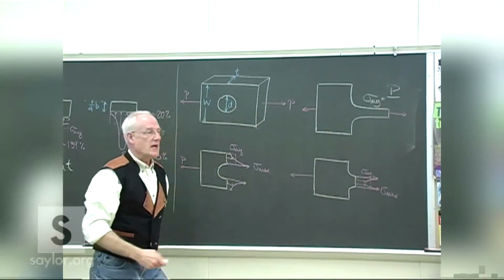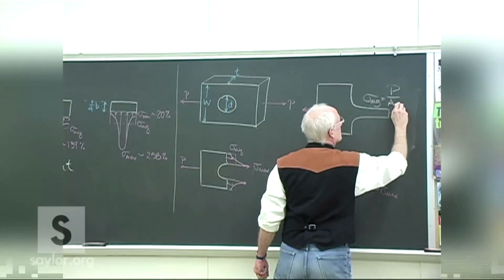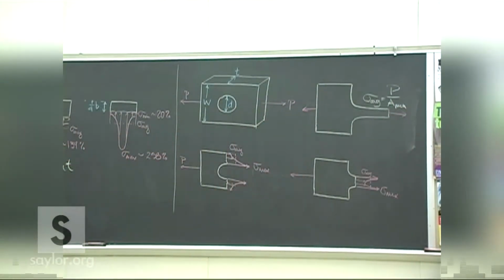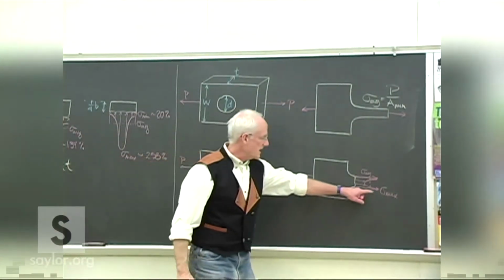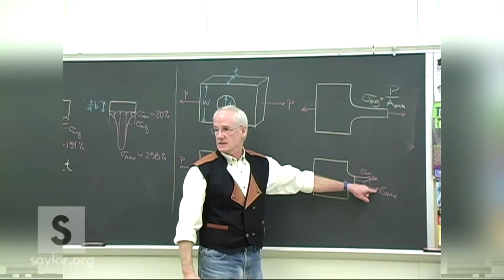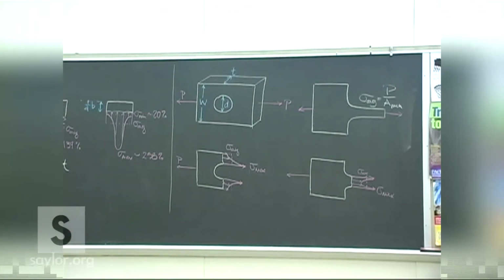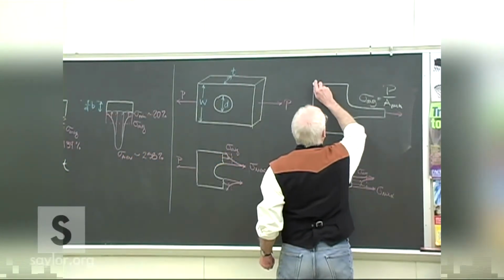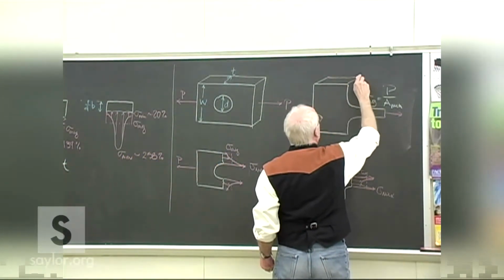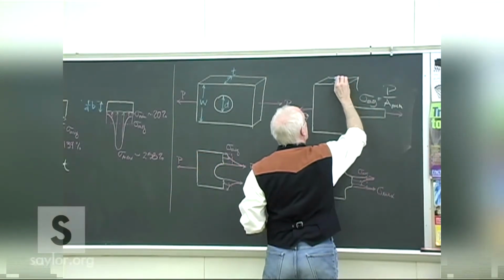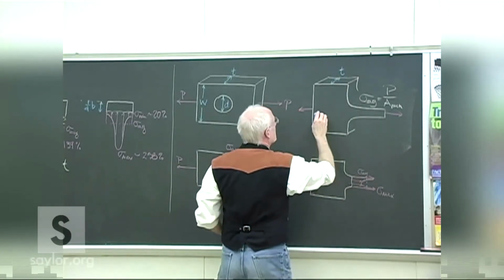The load doesn't change, but the area changes. So we use the minimum area to calculate what the stress is. But even that grossly underestimates what the maximum stress is here. So we need to take that into account. And as you can imagine, it again involves the geometry, the thickness of the piece.